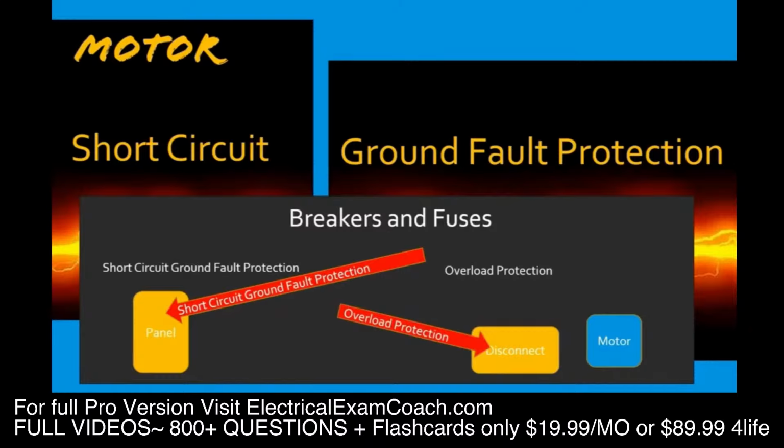The first protection, the short circuit ground fault protection, what do you think it protects against? That's right, short circuits and ground faults. Okay? The second protection, the motor overload protection, does exactly what it sounds like. It protects against overloads of the motors. And what that does is protects the motor windings, and the wire going from the disconnect to the motor.